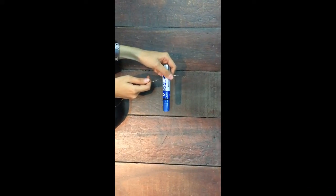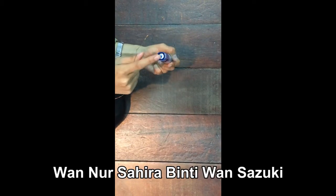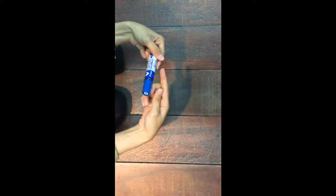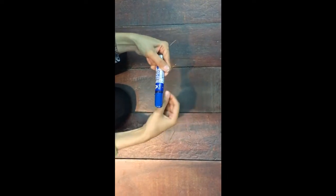The first thing you need to make is the emitter coil. For this, you need a bottle that is about 1.5 inches in diameter. Then you have to take the magnet wire and make 12 turns around the bottle. After the first 12 turns, take the wire and make a twist in order to have a center tap. Then make another 12 turns. Cut the wire, and now we have 3 connecting points: the starting point, center tap, and end point.